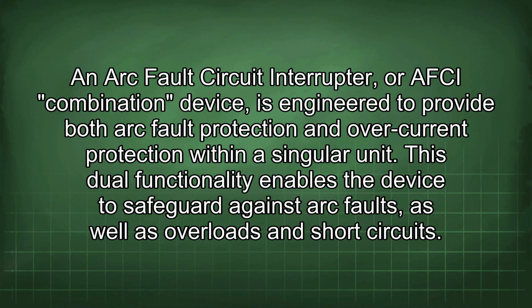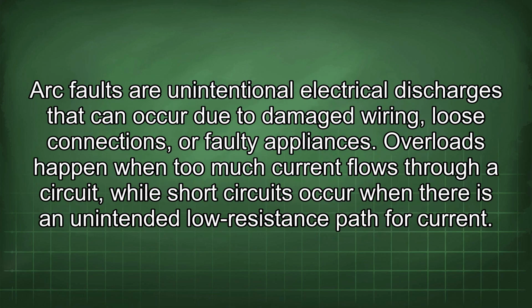An AFCI combination device is engineered to provide both AFCI fault protection and overcurrent protection within a singular unit. This dual functionality enables the device to safeguard against AFCI faults, as well as overloads and short circuits. AFCI faults are unintentional electrical discharges that can occur due to damaged wiring, loose connections, or faulty appliances. Overloads happen when too much current flows through a circuit, while short circuits occur when there is an unintended low-resistance